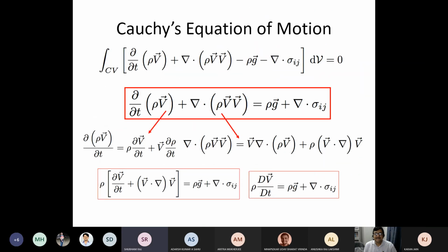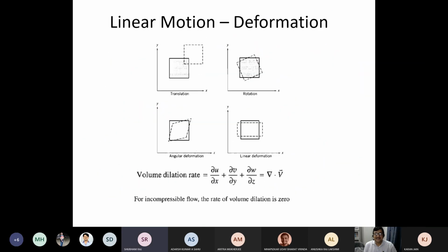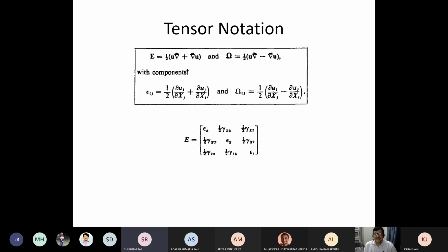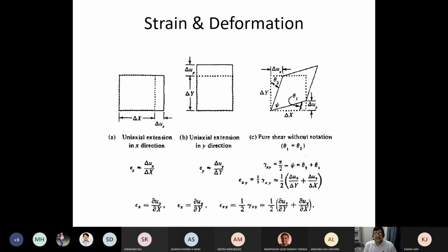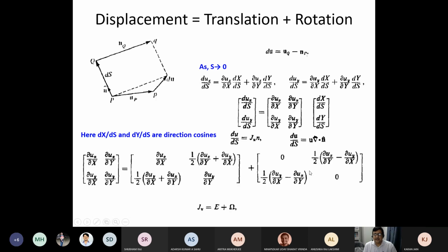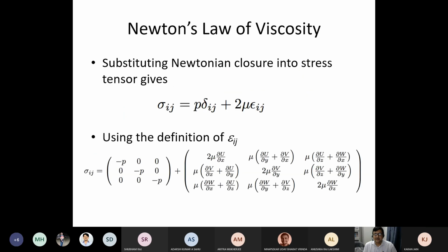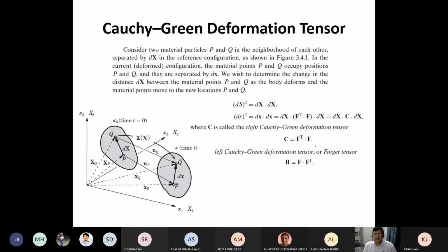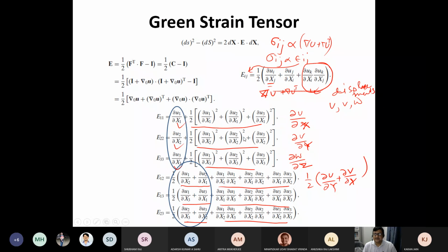A small displacement, like the chain was small. Yeah, so this is the assumption that we were enforcing, that this is a small deformation problem, right? Since we were considering this to be small deformation, we could get away with this because this we did not really consider. Actually, theta 1 plus theta 2 is not this, but if you take all the geometrical arguments together, then theta 1 plus theta 2 will be something like this.